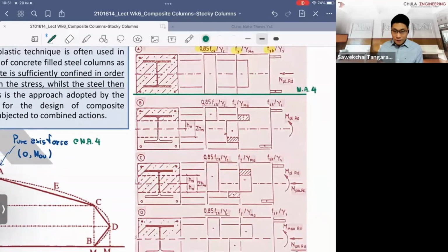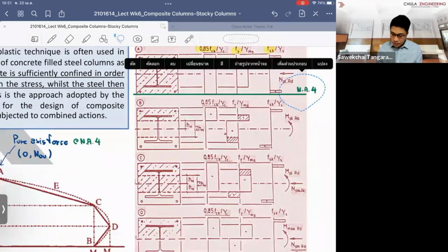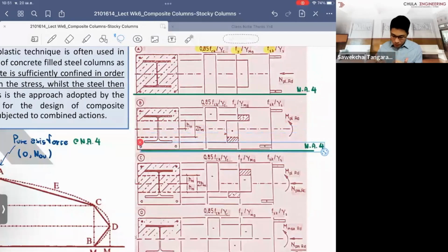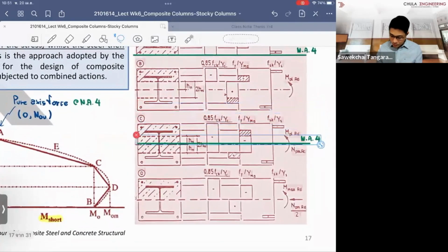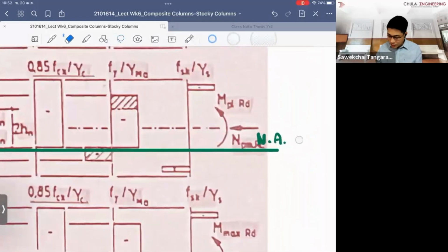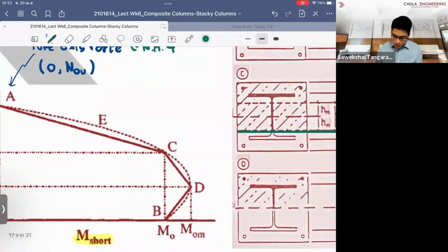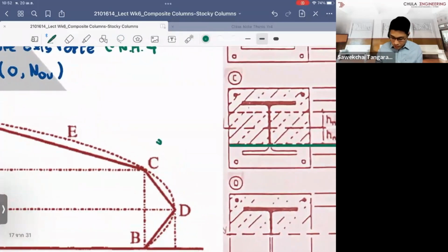And what we do after this is keep lowering the neutral axis step. No, we do not lower, we have to raise it up. When we raise it up from the bottom, we go somewhere here, and we say that at this level the neutral axis step corresponds to point number 3, the one here.